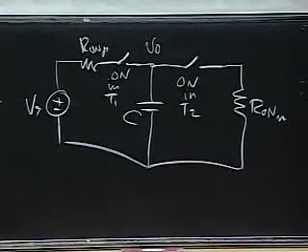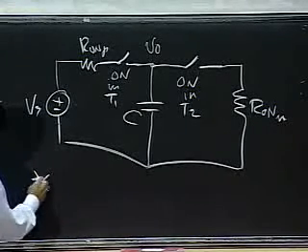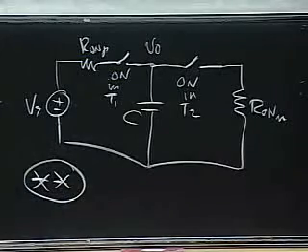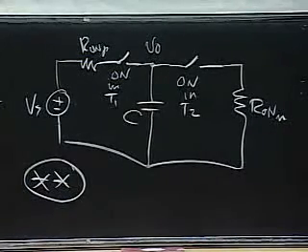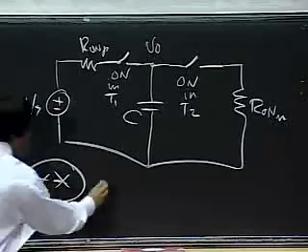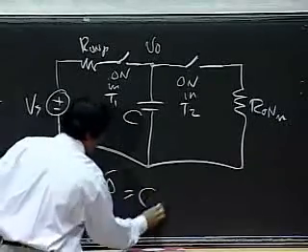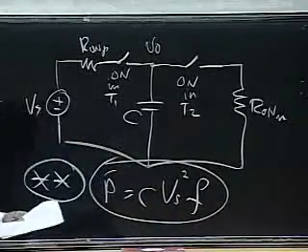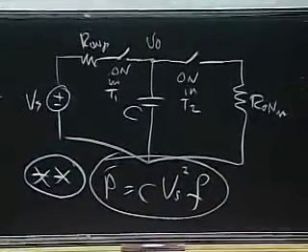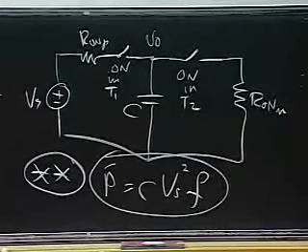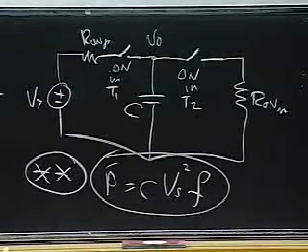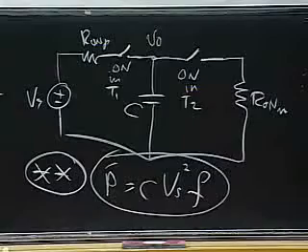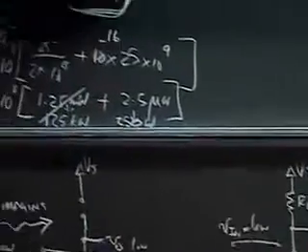And remember, this is exactly the circuit I had analyzed in the last lecture, with the result given by the double asterisk. That result was simply average power being C Vs squared F. That's the exact circuit we used to compute the dynamic power C Vs squared F. So we're done.